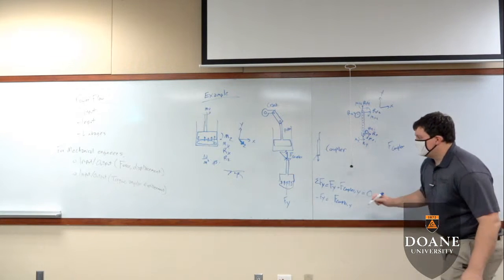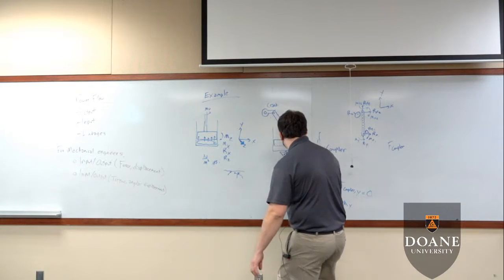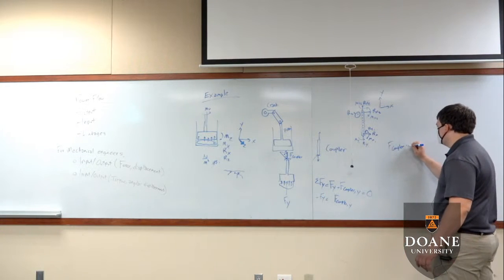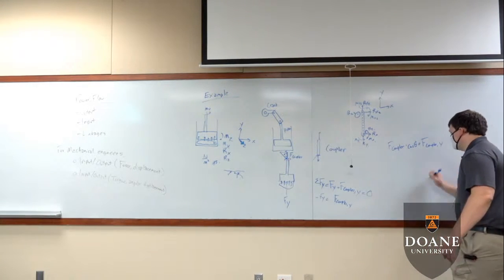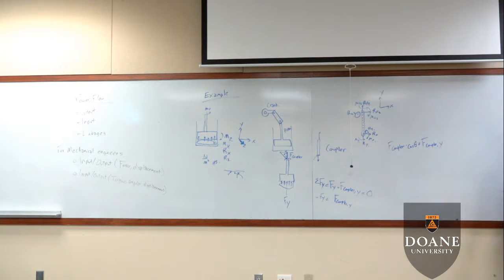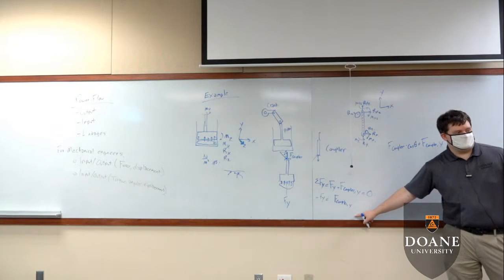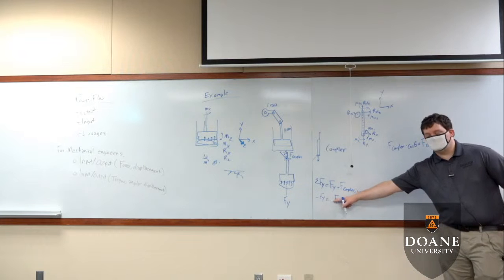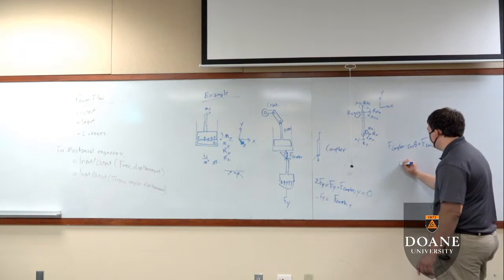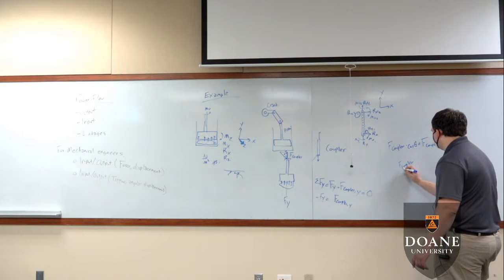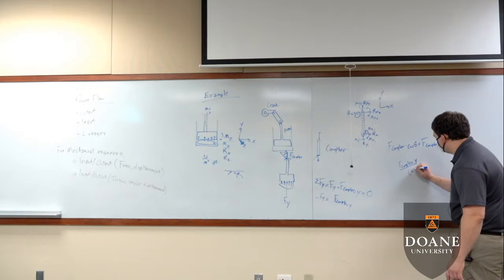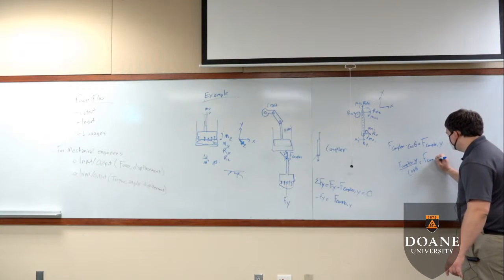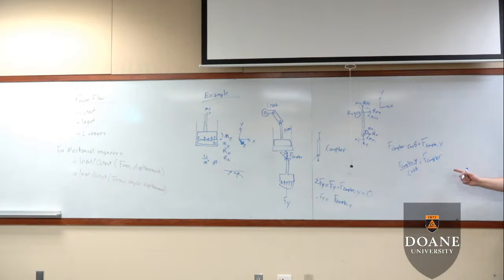For that reason, if we know this angle here, theta, then we know that F coupler times the cosine of theta is equal to the y component of the F coupler force. So if we want to solve for F coupler, since we know what the y component is, it's equal to Fy. If we want to solve that, we have to divide F coupler y by cosine theta, okay, to get the total force that's being transmitted through our coupler.